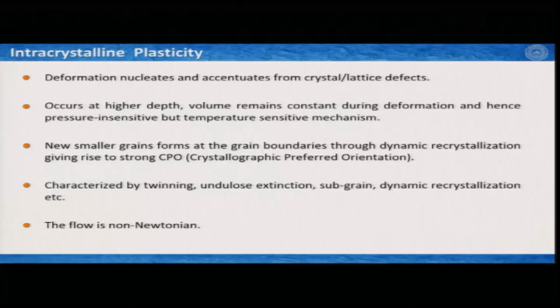So, here are some basics of intracrystalline plasticity. Unlike cataclastic deformation, in the mechanism of intracrystalline plasticity, the deformation generally nucleates and then accentuates from the crystal or lattice defects. So, we learnt about what these crystal and lattice defects are, and we will see how they help us to understand intracrystalline plasticity better.